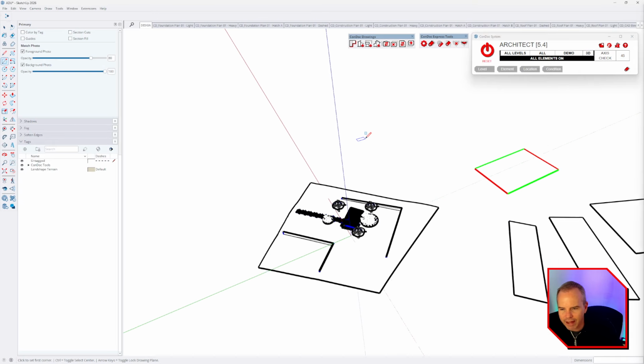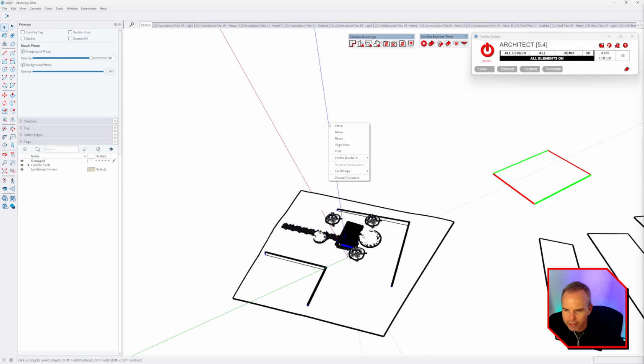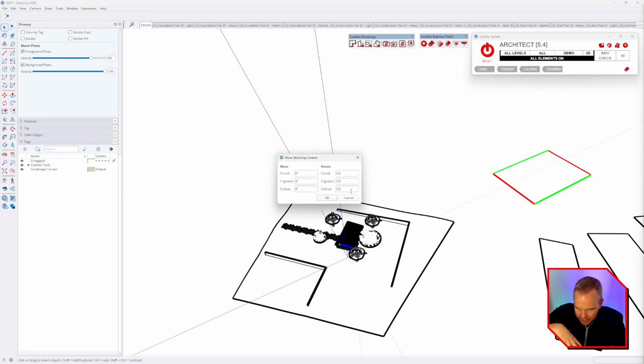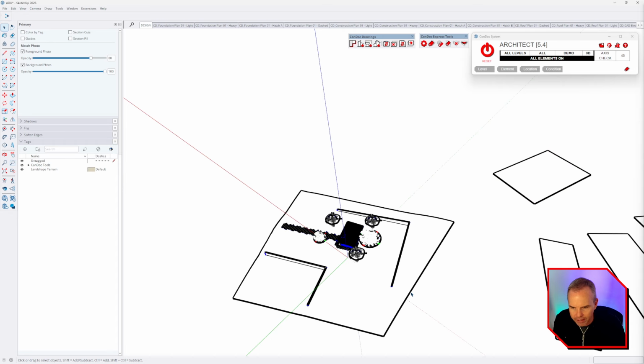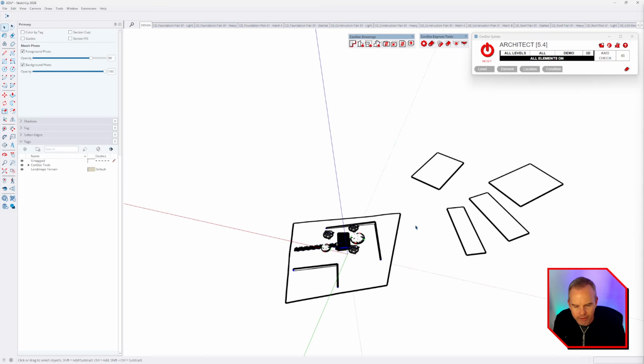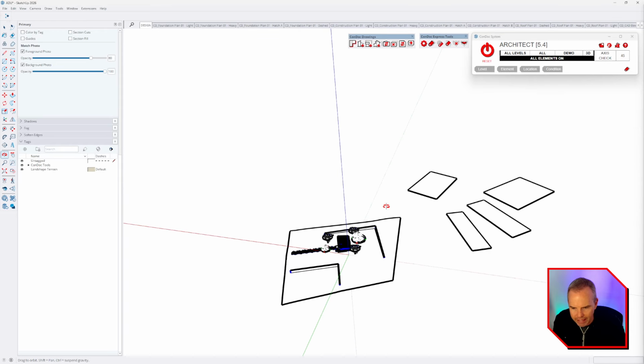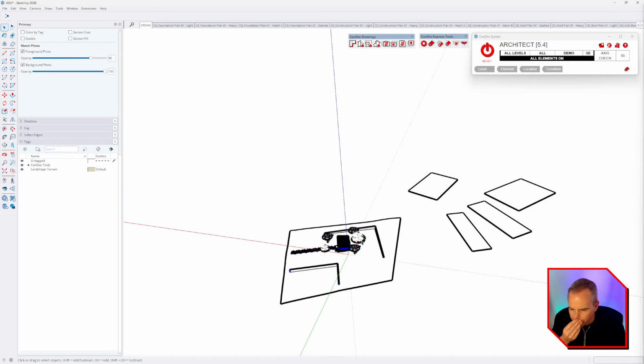The idea with that too is if you were to right click on your axis and then choose move, you can rotate it about the blue, and you could do 22.5 and say okay. So that's what the grid shifts are doing. It's just spinning your axes at a defined distance.